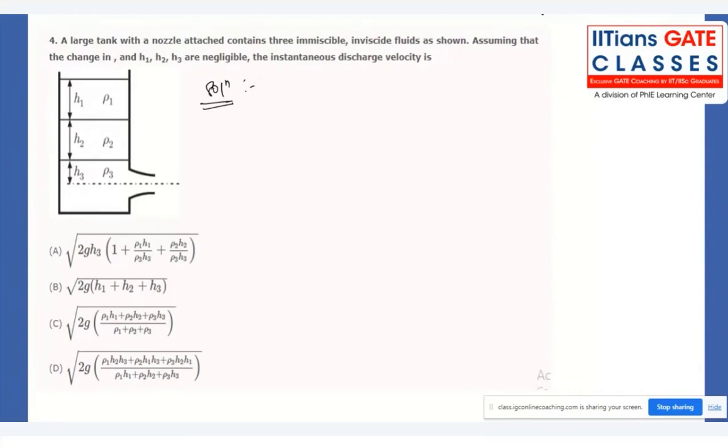So here one large tank is there, containing some immiscible inviscid fluid as shown in the figure. Three fluids are given of respective heights h1, h2 and h3. They are asking what is the instantaneous discharge velocity here. So we can apply the Bernoulli equation here. The top surface will be the free surface. Let me consider this to be point 1.